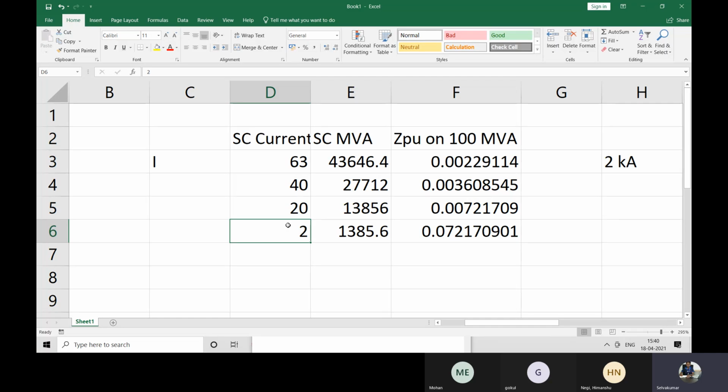So logically what we need to check is whether we have a lower short circuit current because of a long transmission line, or we have a weak system, so the short circuit current is less. If we have only 2 or 3 machines, like 180 megawatt or 200 megawatt demand isolated systems, then obviously the system strength itself is less, the impedance is more, but the capacitance is less. You are able to visualize the system, right?